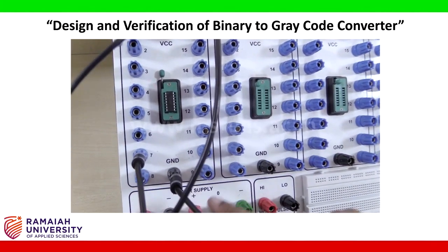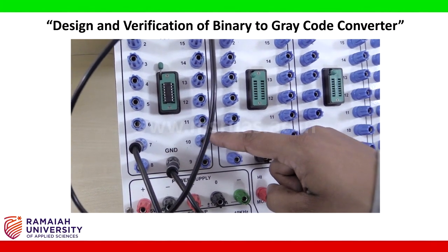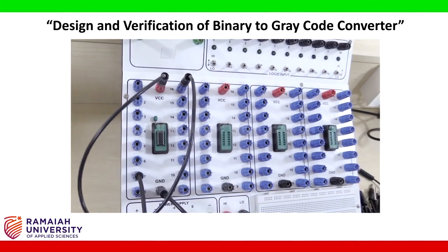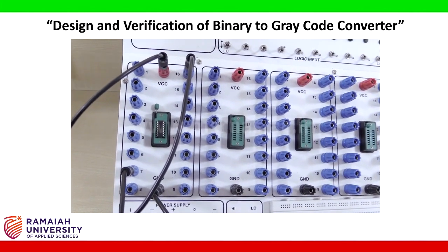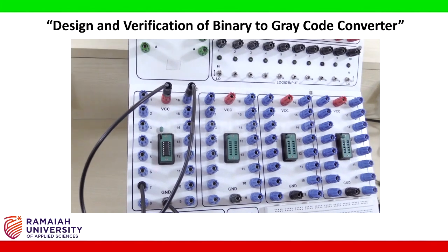Pin number 8 and pin number 9 are not in use. After pin number 7 we have to consider the next as pin number 8 and so on. It will go up to pin number 14. Now as per the logic diagram, there are 4 inputs and 4 outputs. Inputs are B3, B2, B1 and B0. Outputs are G3, G2, G1 and G0.